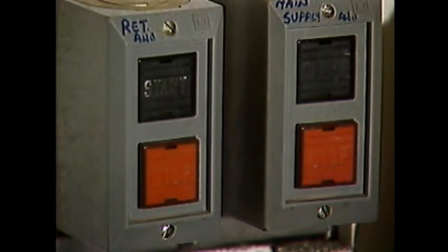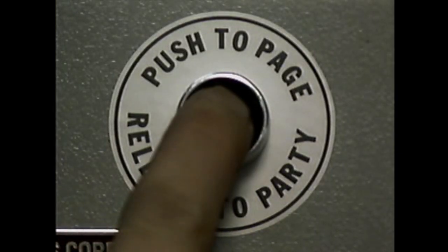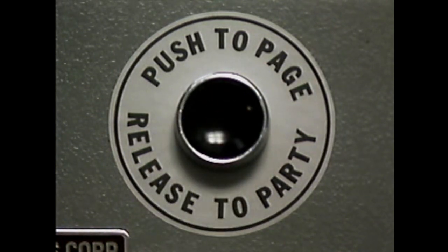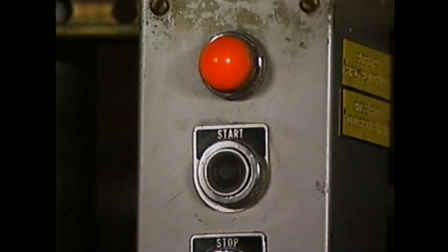Two types of switches that operators commonly use are push-button switches and rotary switches. Push-button switches can vary in design. For example, when some push-button switches are pushed in, they stay in on their own. Others must be pressed and held as long as the switch is expected to operate. When the push button is released, the circuit is de-energized. Still other push-button switches are simply pressed and released to complete an electrical circuit.